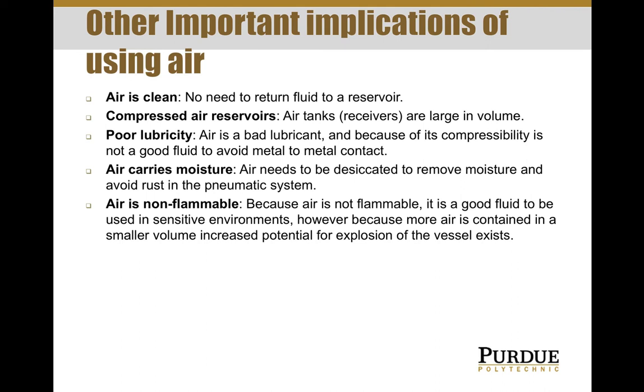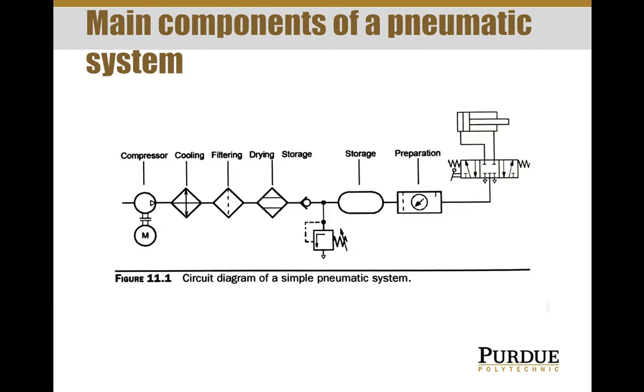Air is non-flammable, so this is an advantage, no question. However, when you have a pressurized vessel, you have to be extremely careful that if there is a puncture, or any foreign object that can puncture the vessel, be super careful, because this can create an explosion of the vessel. This is a compressed fluid after all, and so special care needs to be placed for these compressed air vessels.